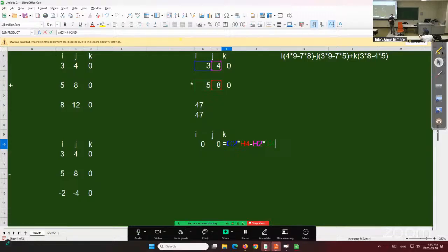Bang, you get directly a single value. You don't care that it's K or whatever, because all you want is the offset. So in the case of a plan, it's super easy to set up your X, easting, northing, station, offset in the table, just simple formulas based on this. Okay?